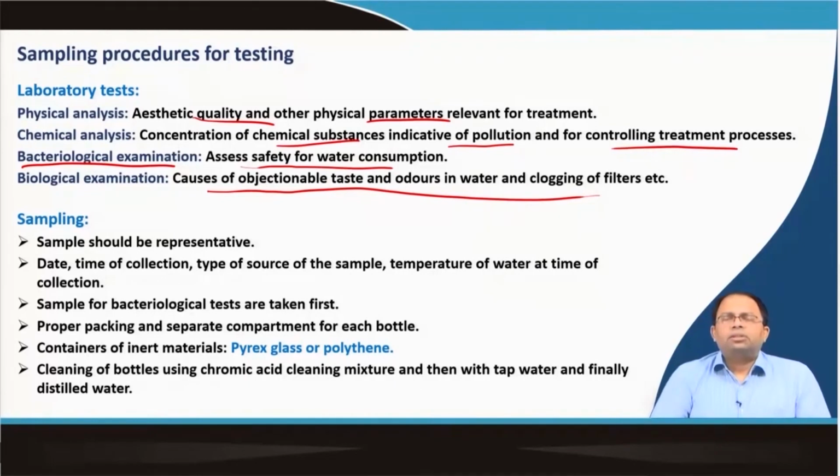So, how do I sample? Sampling of water has to be done carefully and following certain procedures. Otherwise, we will get results from testing which would not be based on the actual water that we are testing, but based on what was already in that bottle or the material of that bottle that we are using and so on, right.